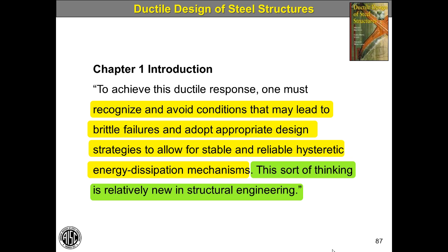You see, the inherent ductility in the steel is what we see with uniaxially loaded specimens in the laboratory. But if we do things wrong in design, this same ductile material may not behave in a ductile manner. And we need to understand that because our welded connections need to be designed with this in mind.